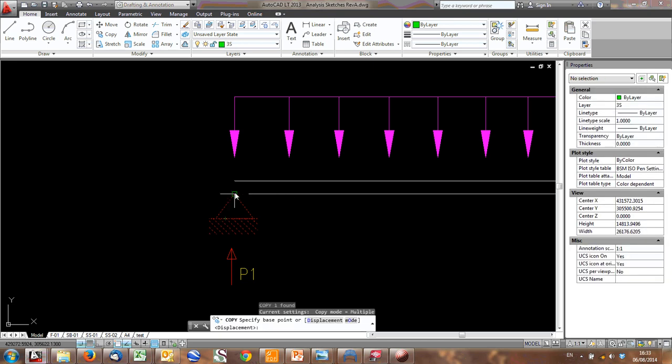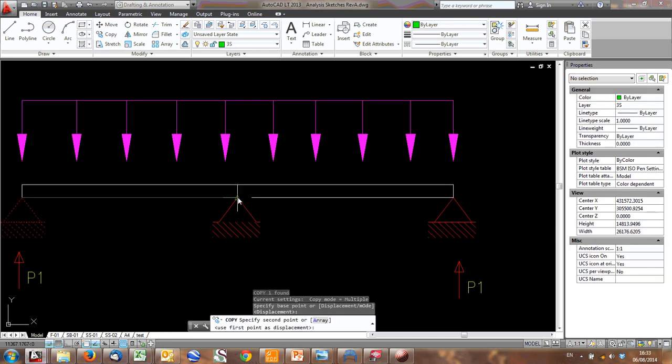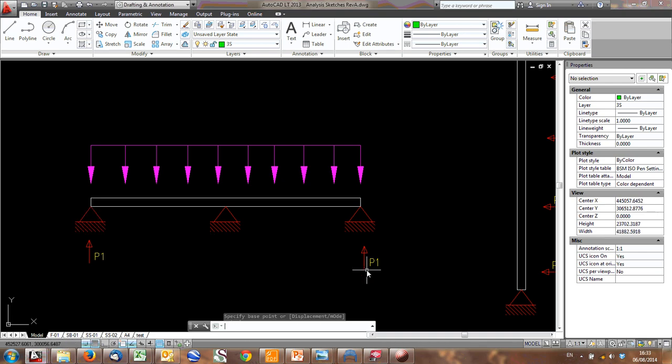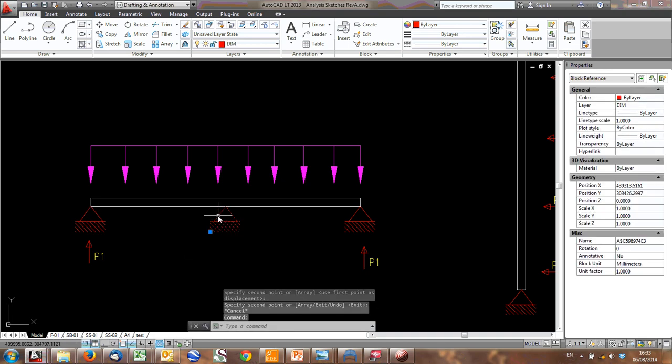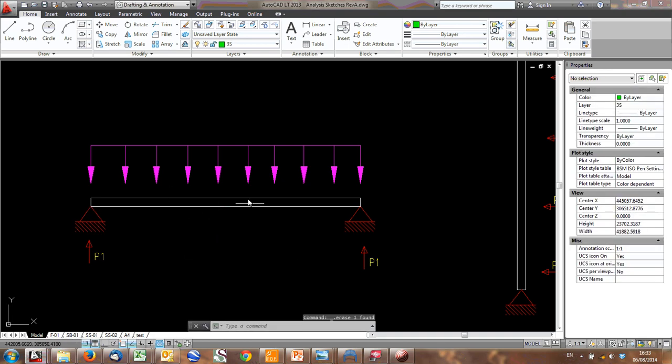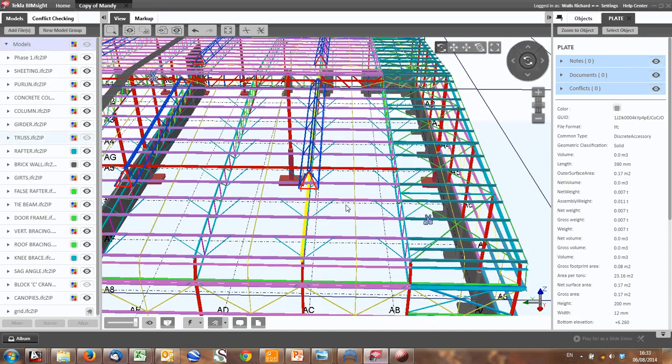I'm just going to copy this across. We're working in AutoCAD Lite right now just to do some of the sketches. There we go, so that might be your purlin. Normally, you can often just design them as simply supported, but you may need to check for multiple spans depending on what's stipulated, or you can just state that purlins come in single pieces, but often the contractors like to erect these covering multiple bays.